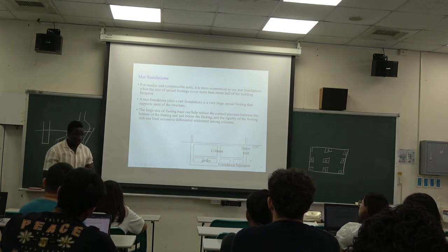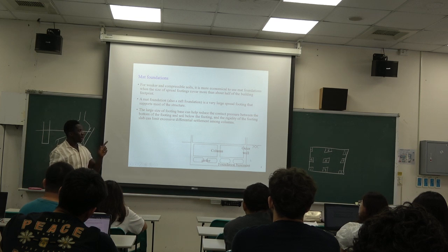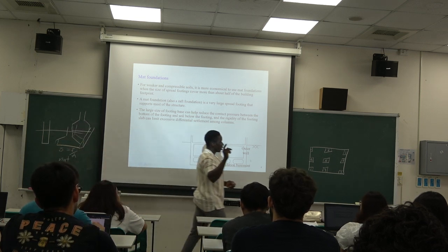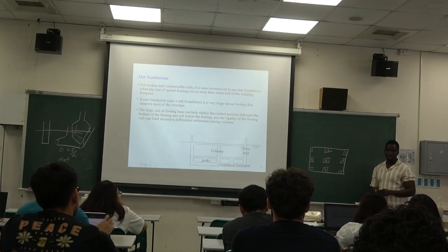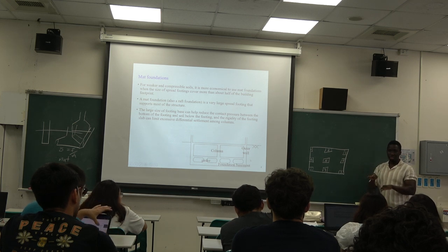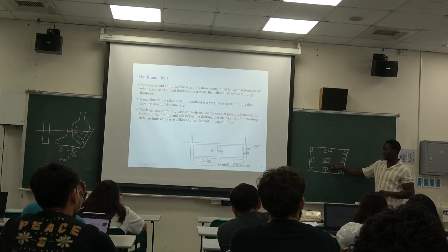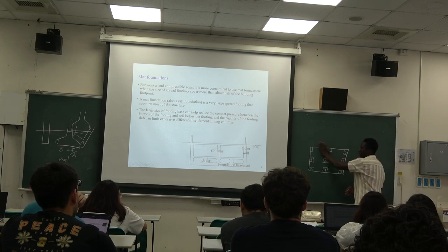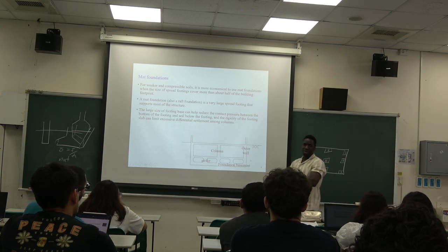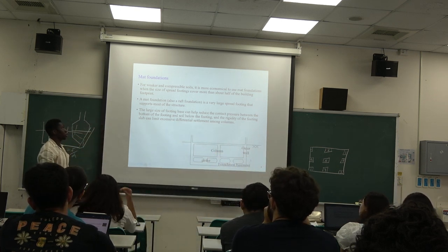Because if the soil is easy to compress, what happens? If you apply the loading, it will settle, right? And if that happens, this spread footing and this spread footing and this spread footing are independent of each other. So you will have uneven settlement. The rate at which this footing will settle and the rate at which this will settle and the rate at which this will settle might not be exactly the same. So you will have problems. But if you use a mat foundation, then the settlement will be more even if you have a settlement. So that's also another scenario.